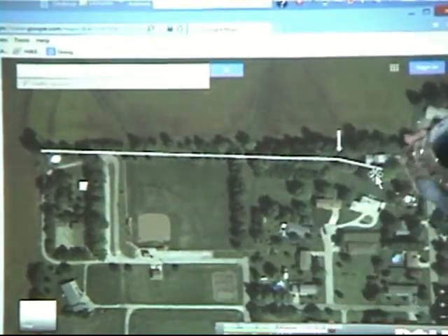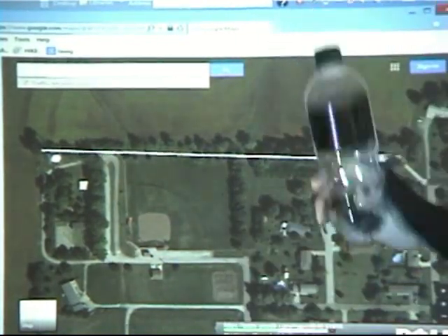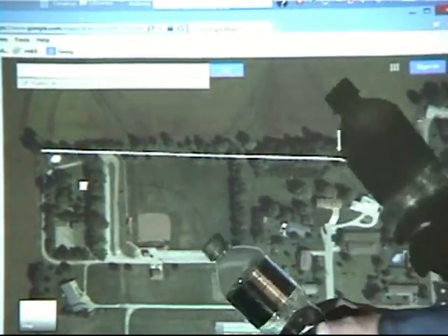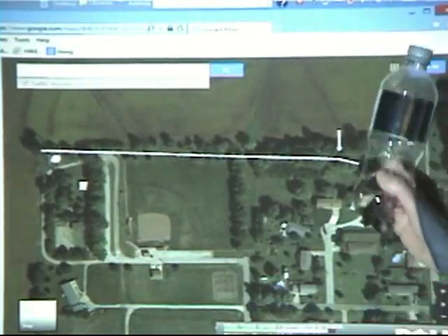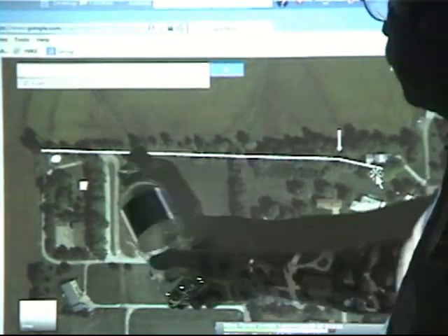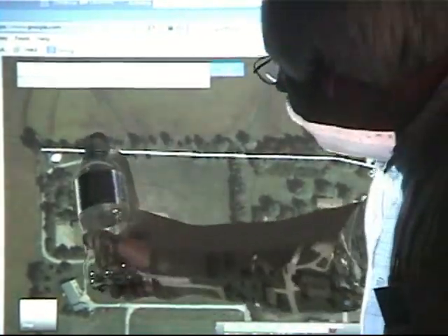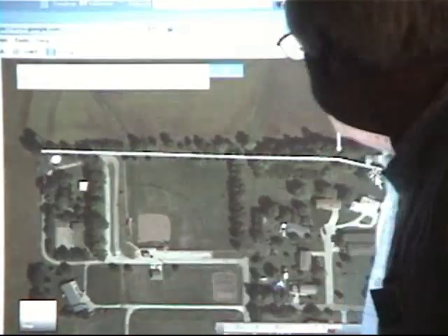Actually, I use it on 80, and it's a 160 meter dipole fed in the center with 250 feet of 450 ohm line. Obviously, not everybody can do this. And I strung this through the trees. Kevin climbed the tower, and I went through all kinds of contortions to get over a bunch of trees here and terminated it out there.